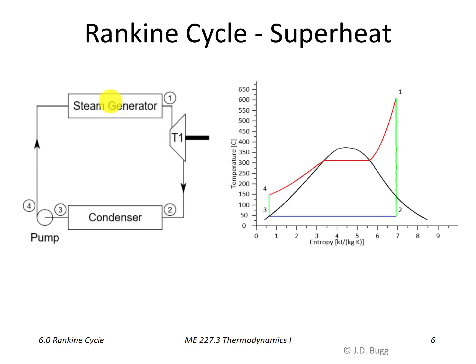And the effect on the TS diagram is to move this turbine process from 1 to 2 from here, where it used to be, out mostly into the superheated vapor region. So this is still a line of constant pressure. So all the way from 4 up here, across and up, that's a line of constant pressure at the steam generator pressure. So the exit of the steam generator, entrance to the turbine, is at this point here. So because we've added more heat, we've moved the turbine process to the right. Therefore, this portion of the turbine is dry, meaning there's only vapor in it. It's only at this bottom portion where we start to get a little bit of liquid showing up in the turbine. So that is a much more realistic cycle.